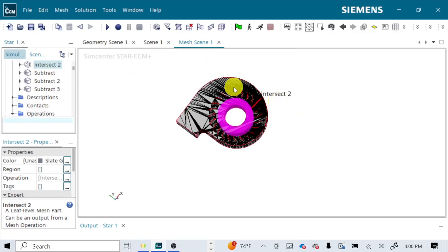Now, again, depending what type of fan you're looking at, this in principle works just fine for axial fans, but those have to be 3-dimensional by nature. This is a blower fan, which kind of works 2-dimensionally, at least sort of, which is why we're doing this. But the exact same process applies: you have to create a region for the air in front of the fan or around the fan, depending. If you have free spinning blades or even blades in a housing, the blades can be entirely encapsulated in a region of air that rotates, and then everything outside of that doesn't rotate.